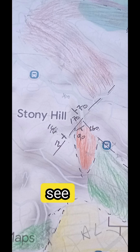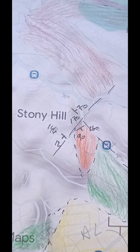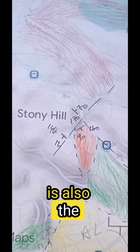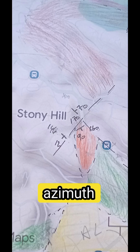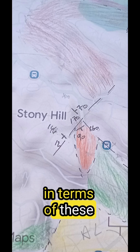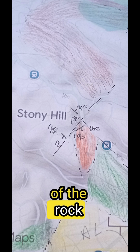Now you can see the T, small t, that is a representation of what we call dip and strike. In other words, where are the rocks aligning themselves in terms of their dip, and where is also the strike, in terms of the perpendicular alignment to the north, azimuth north, that is. Now, the dip amount, we can see this in terms of these numbers. So when you can see the 70 or the 90, that is indicating the degree of inclination of the rock strata.